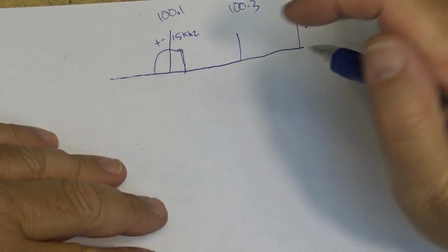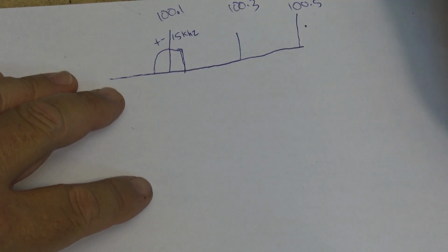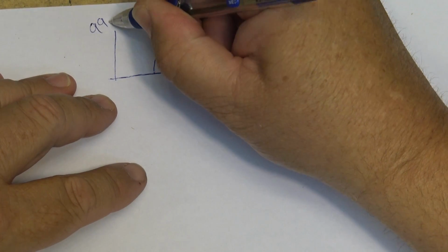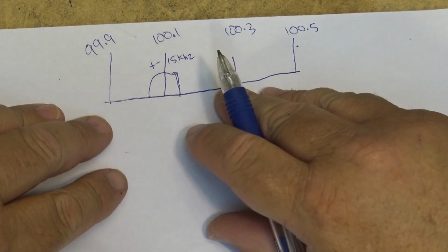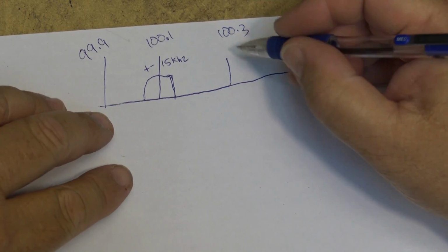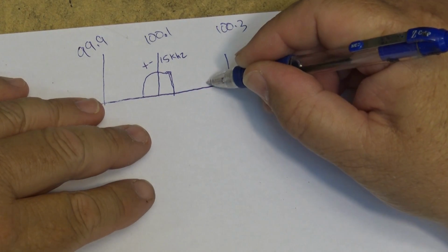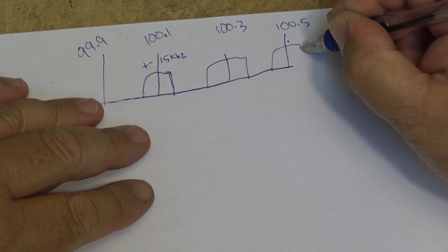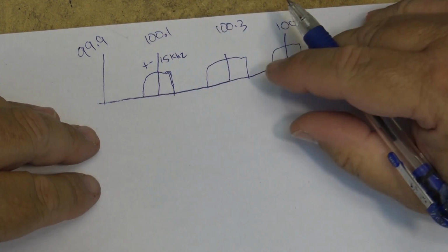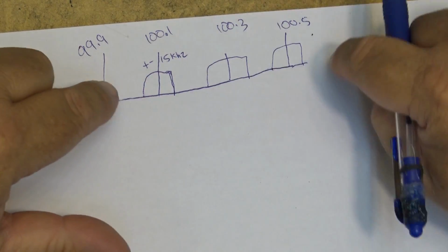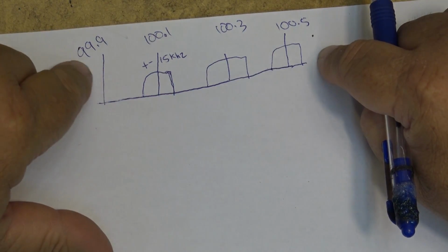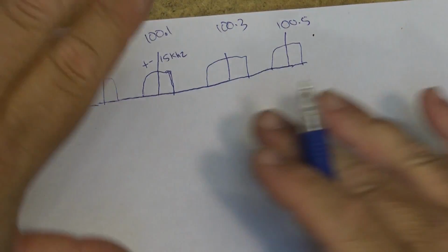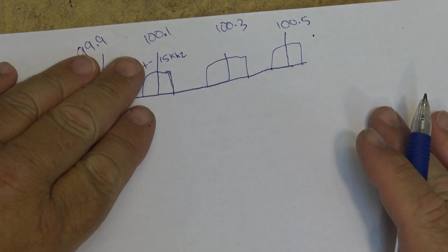So here's our channel spectrum, and of course our next radio station down would be 99.9, right? I'm drawing this like this so you get the idea, because of course if this station here also has their audio, and this station here has their audio, etc., right? This is the spectrum. So you need guard bands in between so that the stations don't overlap with each other. And this other station here would have its audio over here, right? So this gives you an idea how the spectrum is laid out.